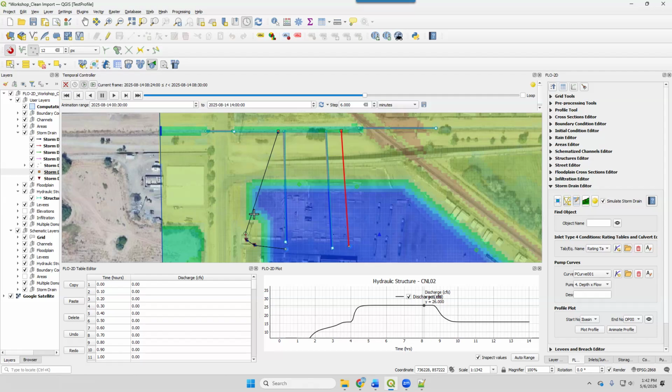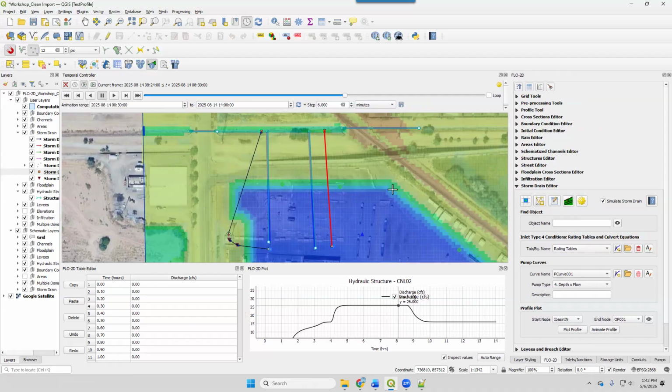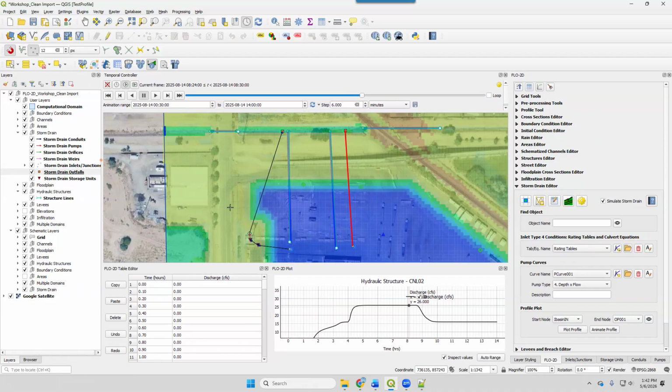And that's kind of a Flow2D quirk. That's just a Flow2D thing. You can't have a negative slope connected to an outfall, between a node and an outfall of a conduit. Which maybe, now I don't think that's why this one doesn't work, but I suppose it could be. And that is basically the end of the simulation. So I'll go ahead and shut this down right here.